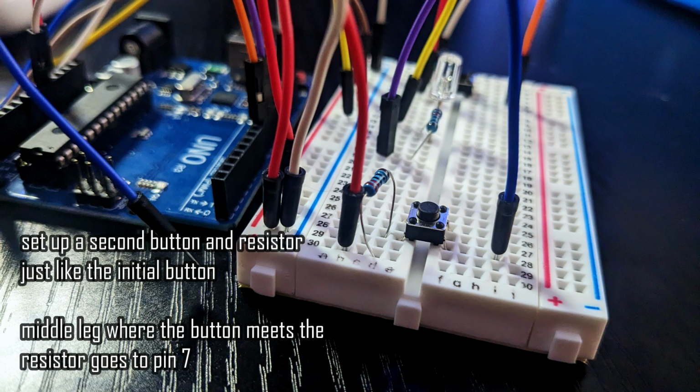So it does say spaceship repair, but then it cycles through the systems without me pressing a button. Pressing the button makes it pause on whatever system is showing, but it doesn't do anything else, and then the LED also doesn't light up. So let's troubleshoot what's making that happen. I feel like we should add in a second button to simulate the repair work.